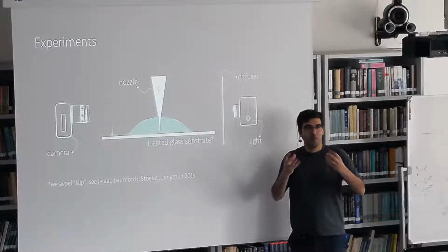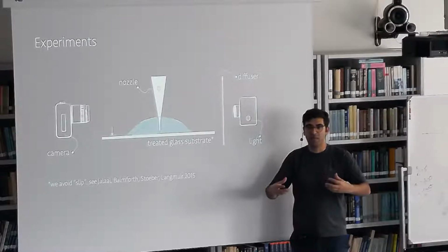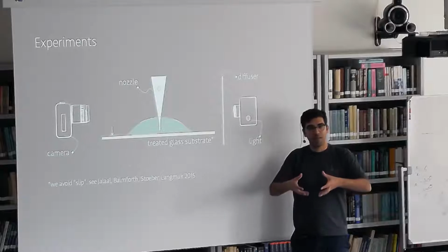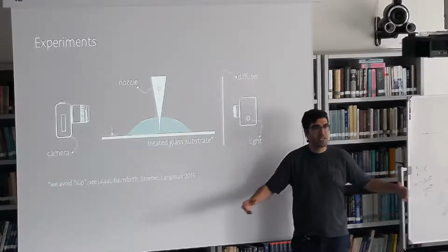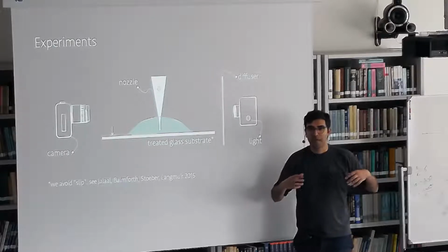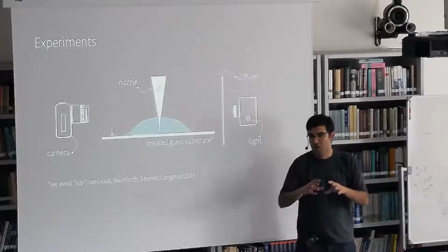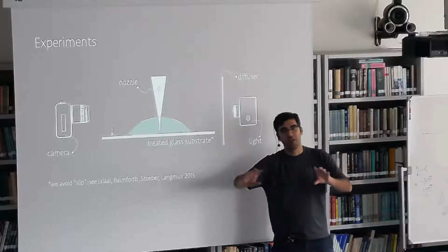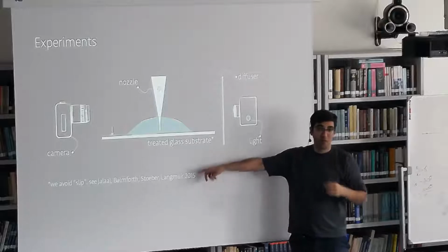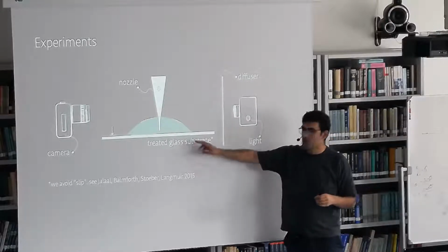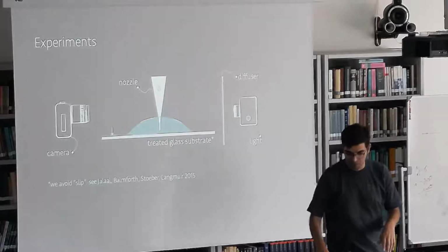They have these polymeric blobs that, when they go close to the surface, there's elastohydrodynamic theory that shows how they deform, and the solvent remains underneath the polymer, so you get an apparent slip. So it's not Navier slip or something. It is as if you have a very solid thing that moves on top of another solid. So it's very important to get rid of that if you want to compare with theory. We did that by treating the surface chemically. So we now know that there's an easy solution for that.